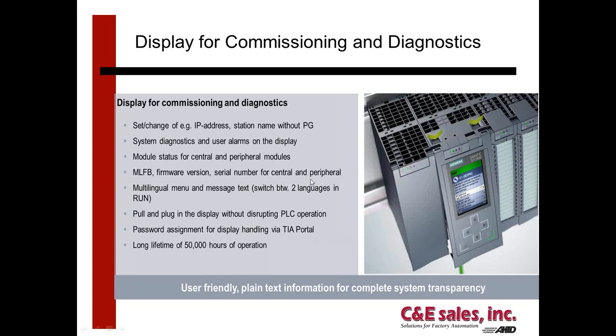Huge feature, system diagnostics and user alarms. We can display those right on the HMI or right on this little HMI panel on the PLC. This next feature, module status for central and peripheral modules: it used to be I had to get online with the PLC via hardware configuration to see what basic faults were occurring in a module or in a distributed I/O module. That now is appearing right on the panel of the PLC. Very large benefit for maintenance or even engineering if you don't have a laptop with you.